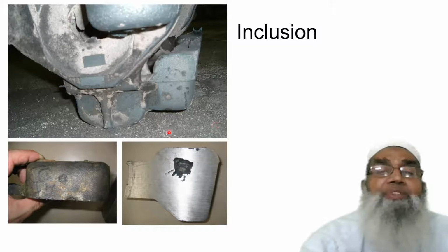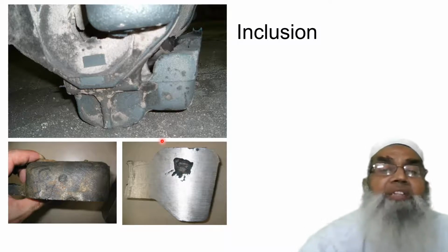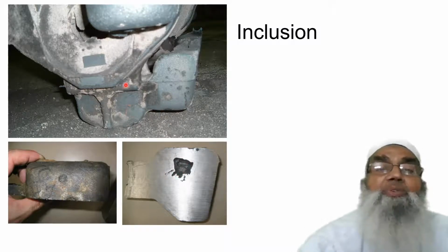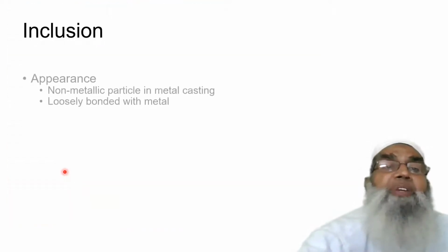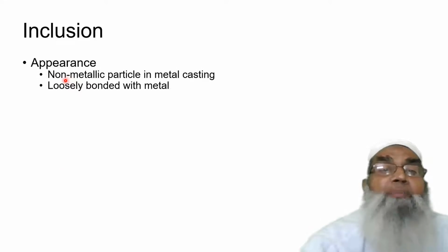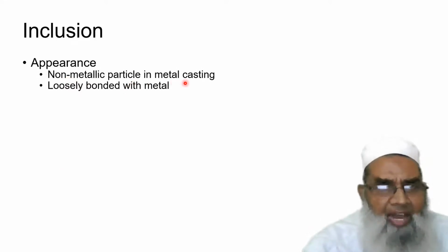Now another is the inclusion, inclusion of sand particles. Here I can see the inclusions. They appear as non-metallic particles in the metal casting.